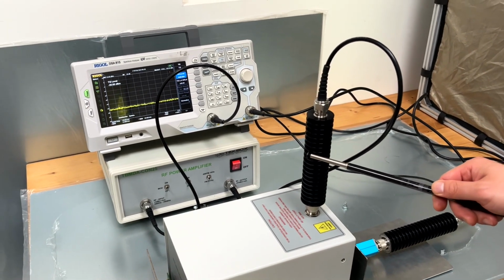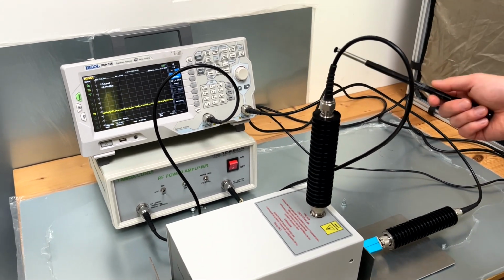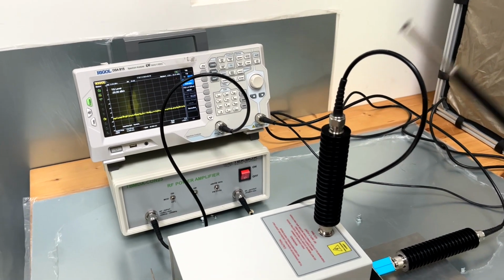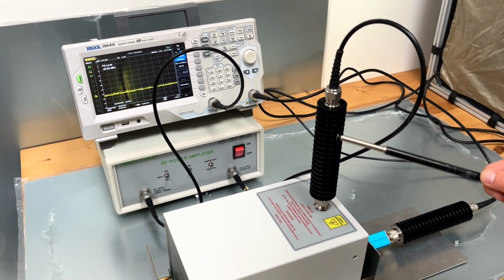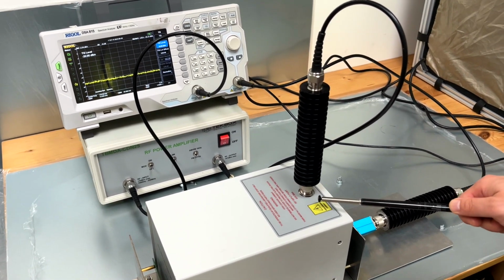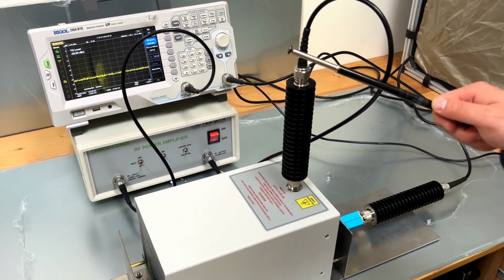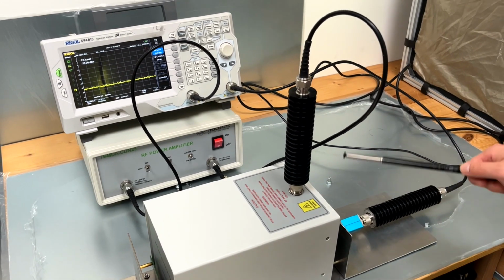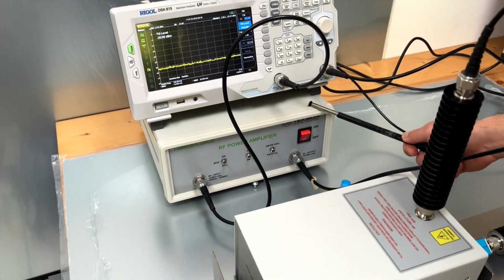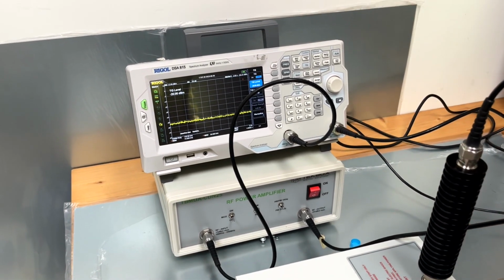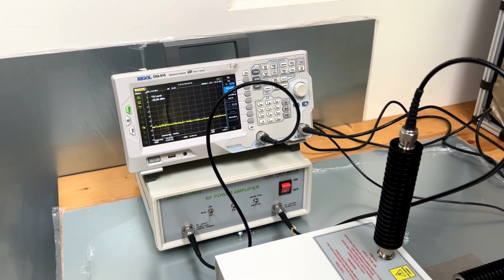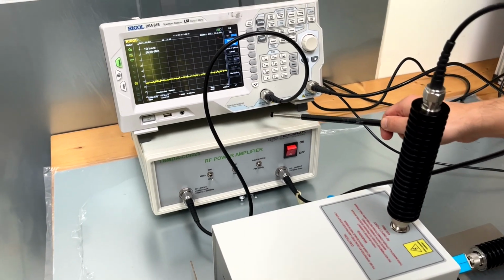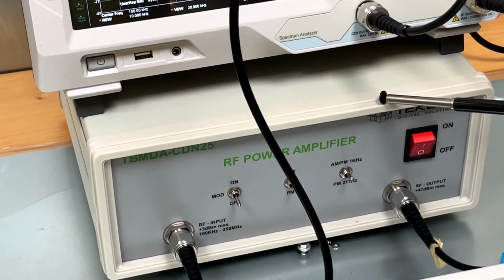A 6 dB attenuator is needed according to the calibration procedure. So from the RF input port, we got this 6 dB attenuator, which is connected to the output of this amplifier. As you can see, for this calibration, we have the CDN 25 from TechBox.